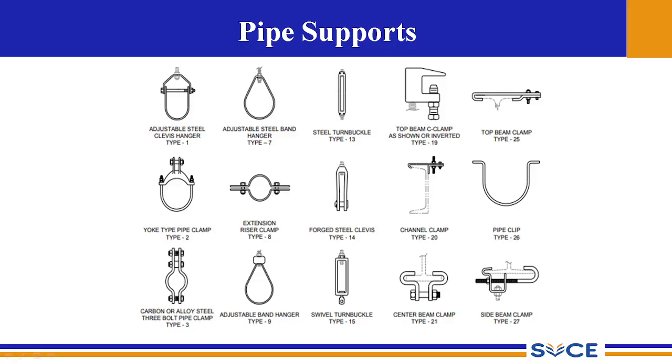It can be rotated, and the vertical adjustments can be provided by this steel hanger, and the pipes can be suspended in the horizontal direction. So this is a pipe attachment for suspension of horizontally stationary lines, and it is providing a means for the vertical adjustment.